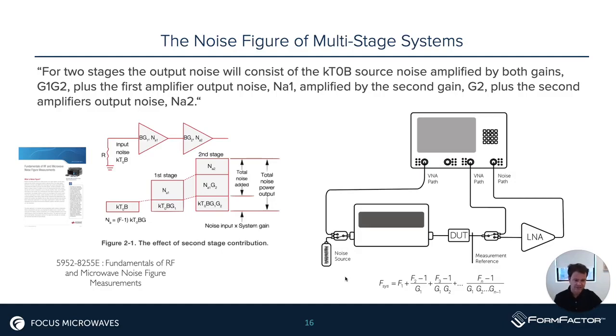So here again, we've looked at this equation. We're going to go a bit deeper on the next slides. But basically, what we're trying to show here is the noise figure of the system is the summation of all these different ratios here. But you could see that the main contributors are going to be the F1, the first item in the path, and the gain of it as well. So if the noise figure is high here, you know that regardless of what's happening here, the system noise figure will be high. Now these components here will be affected by the gain. So if you have a large gain, this component is going to be small, this component is going to be small. So ideally, you really want your first item to have a small noise figure and a very large gain, and that's going to allow you to have a very low noise figure and a very sensitive system.